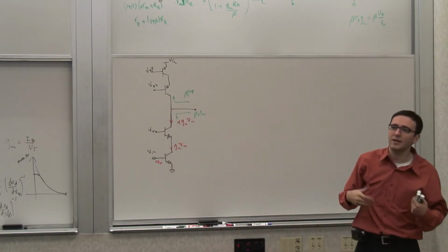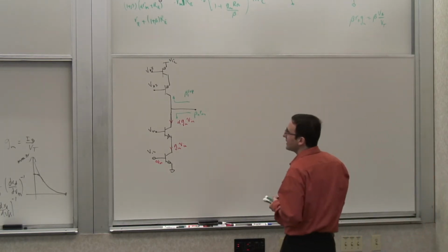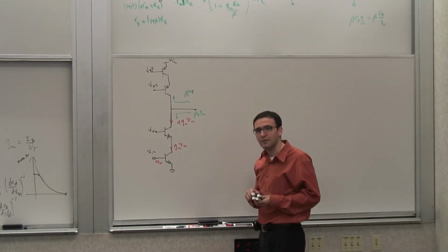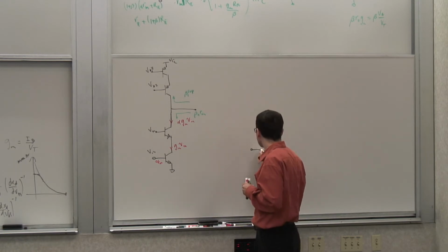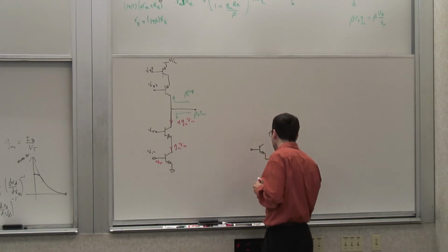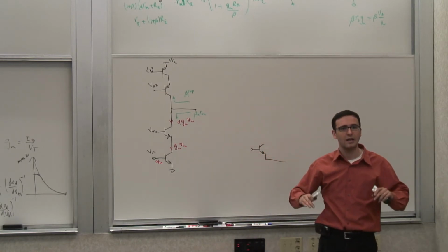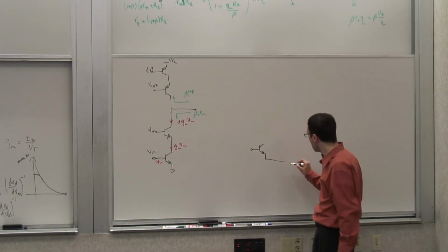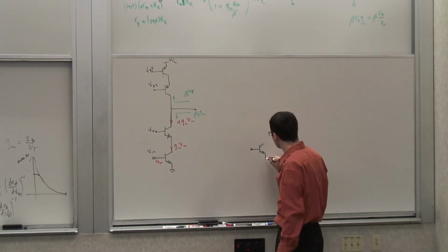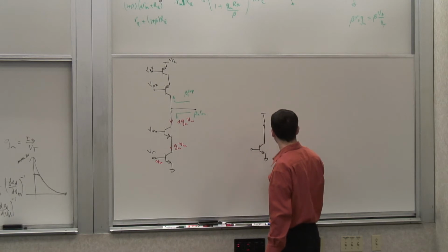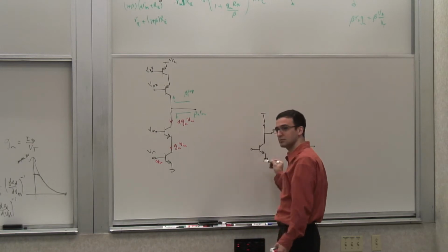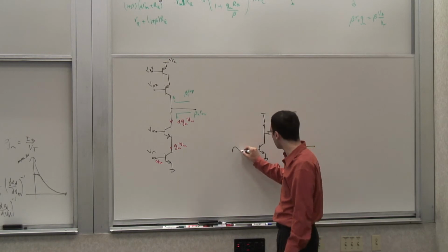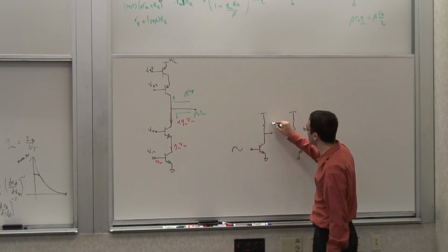And now, we did that in a differential form as well. So, one of the things that we then did was we looked at differential amplifiers. We saw that the idea of a differential amplifier is to make an amplifier whose output does not change when both inputs move in the same way, in phase, the common mode, right? So if I make two common emitter amplifiers, like this, independent of each other, I can apply differential input to this and I will get a differential output at the output, right?